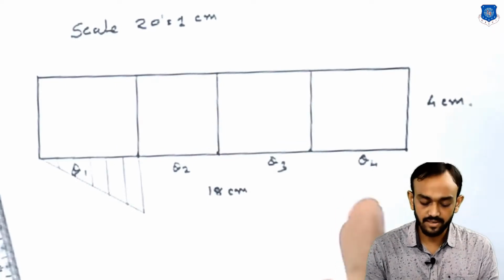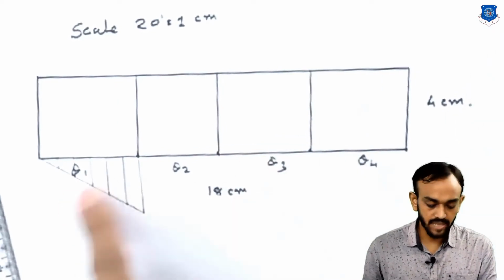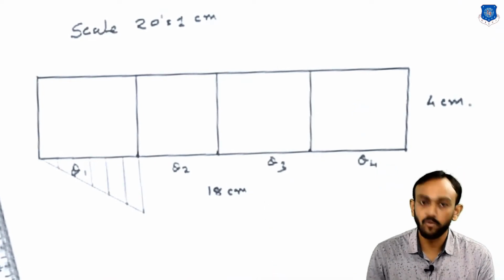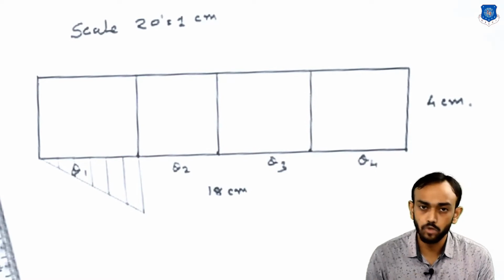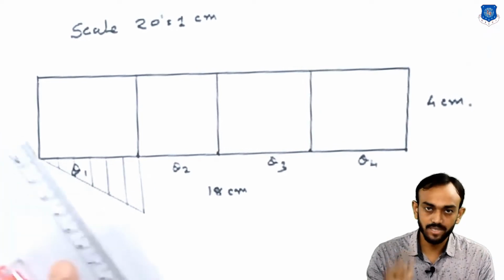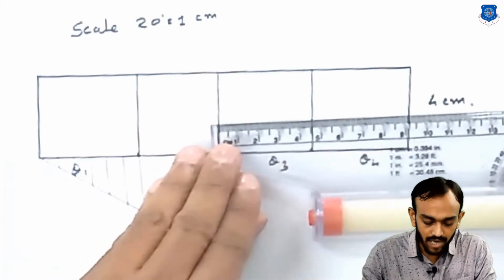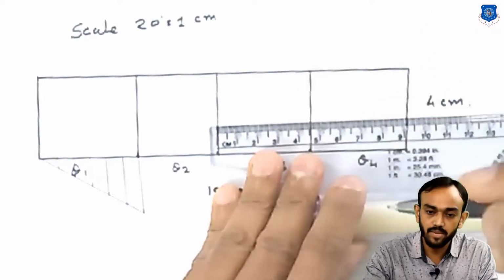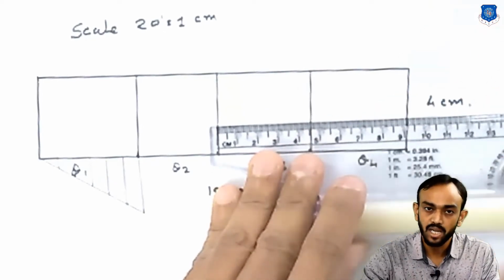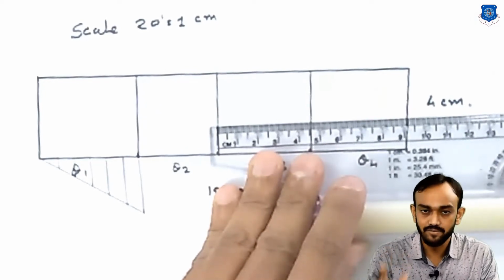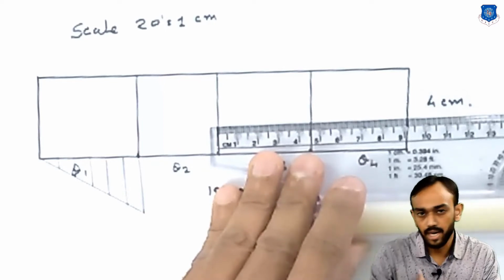When you need to divide this return into 6 parts, you can use the same method here. There is also a second method. You just divide this 45 mm by 6, so you will get 7.5. So each segment will be 7.5. But what is the problem in this method? When you start from here, 7.5, 7.5, there will always be some error in each portion. And what will happen? The last partition will be much larger than the others, or it may be much smaller than the others.